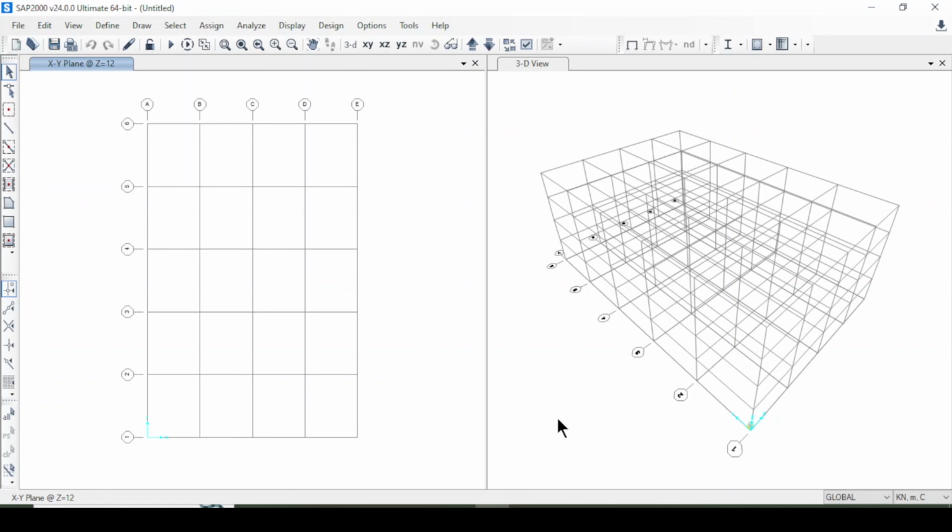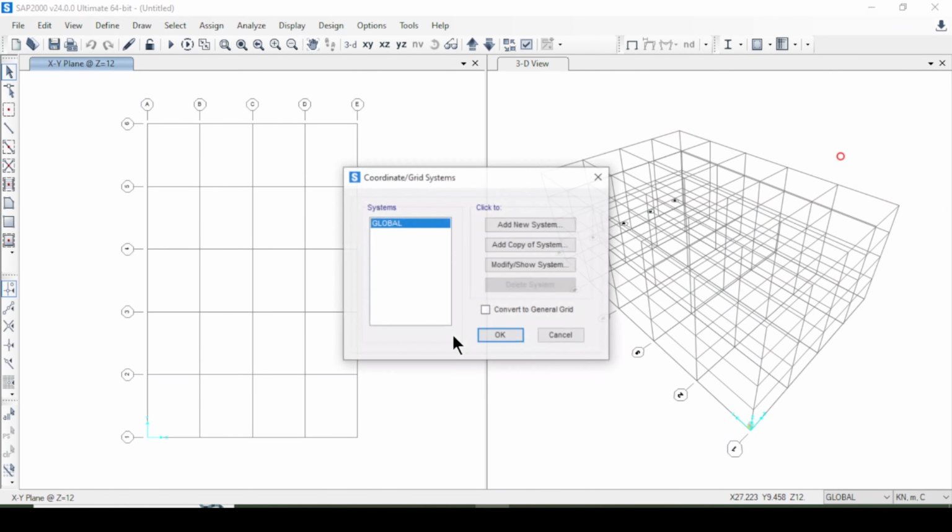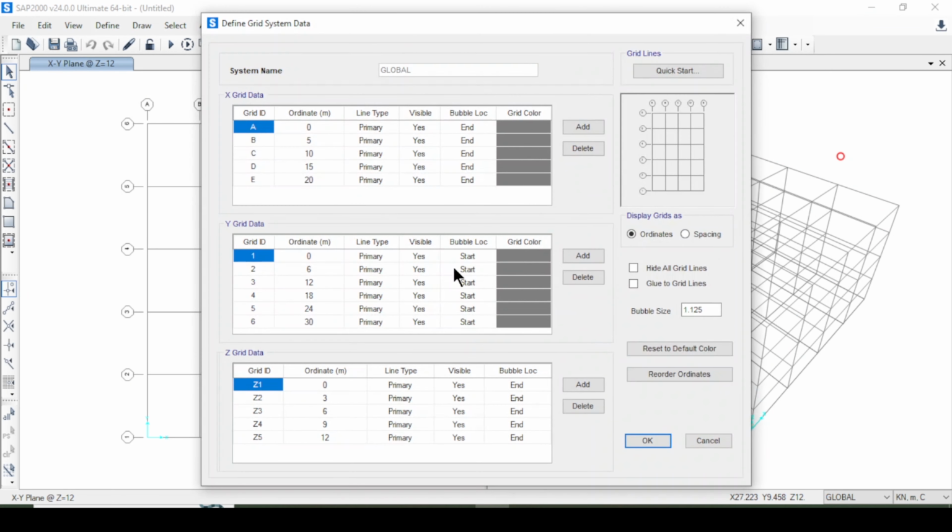Here it is a structure. If you want to just modify, you can just change from here as well, and you can look here to the spacing as well. Like I have 1 story, 2, 3, 4 story, and you can add another one as well if you want. So I will add one, so it will be 3.4 meter. Okay, the first and other will be 3.3.